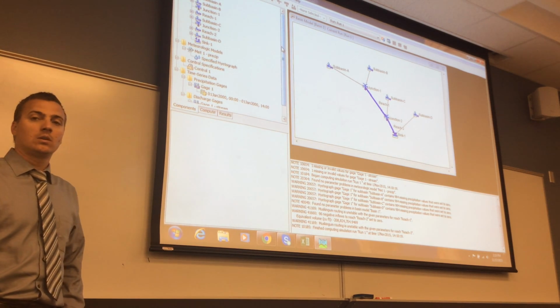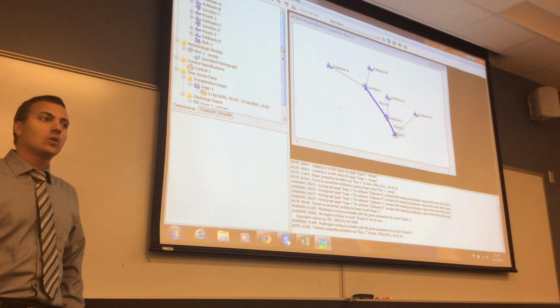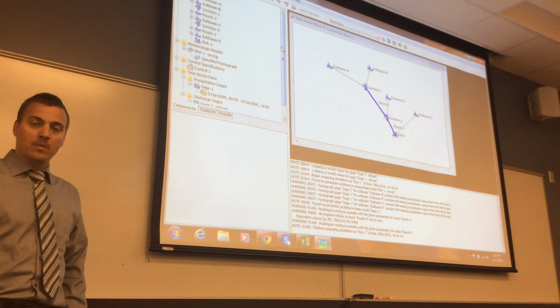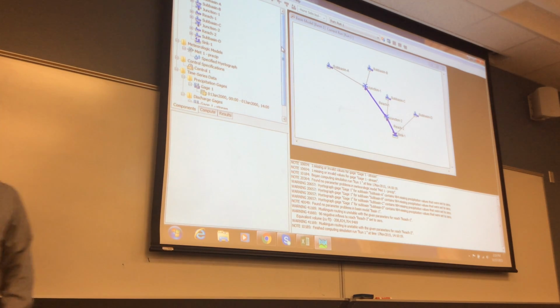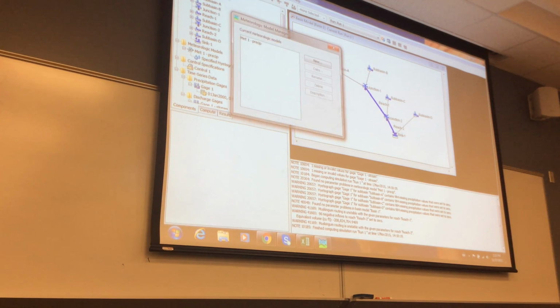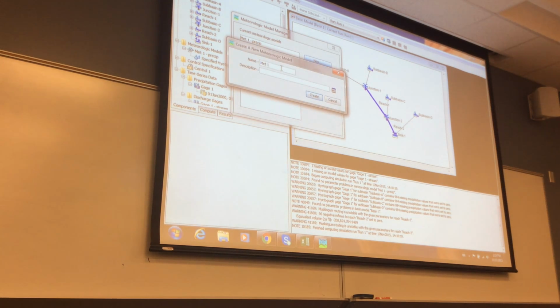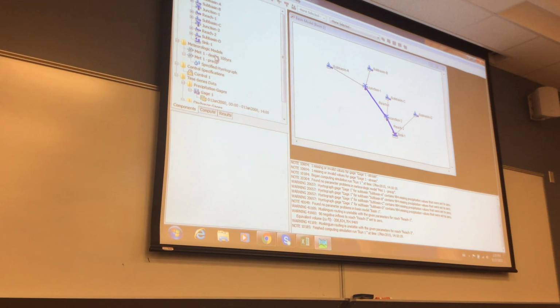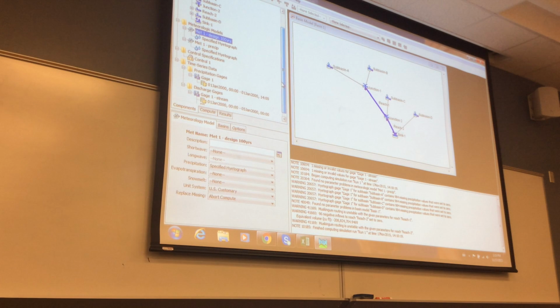We grab the IDF curve, get the intensity, and then use the duration. Exactly. So I'm going to create a new meteorological model now. A new one. I'm going to call it Met1 design 100 years. So now I have a new one here. I click on it.